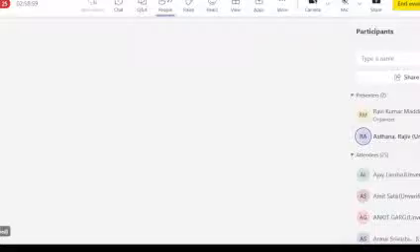The whole idea is to be able to create hollow parts. Ceramic sleeves that we use for thermocouples, they are made using this process. Or different kinds of honeycomb structure, ceramic filters. All of those things are made using an extrusion process. One thing here is that the slurry that you use should not be very liquid. It is more viscous, more thick as compared to slip casting and tape casting, because during extrusion, you don't want the liquid to separate from the powders. So the slurry viscosity is higher in this case as compared to some other processes.